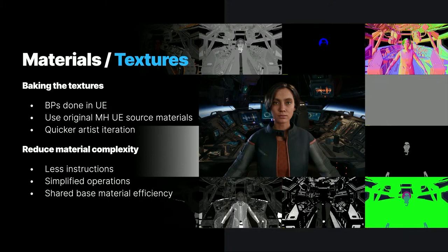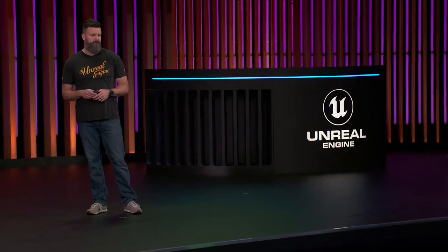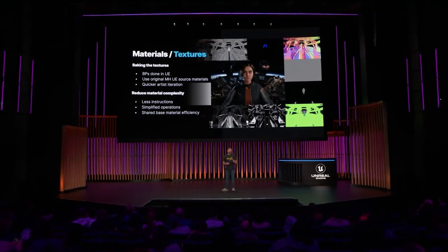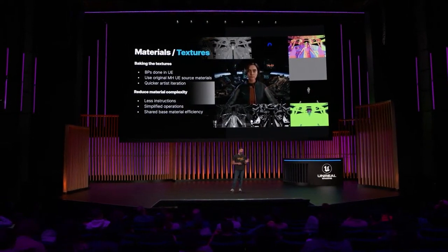The high LOD material has a max of 2K resolution, and this is the resolution cap for UEFN textures. The medium material has a max of 1K resolution, and the low material has a max of 512. We also decided to share one parent base material to be more performant, and allows all materials below it to inherit its parameters. For comparison, the original UE skin material was about 577 megs, and the new UEFN version is about 13 megs.